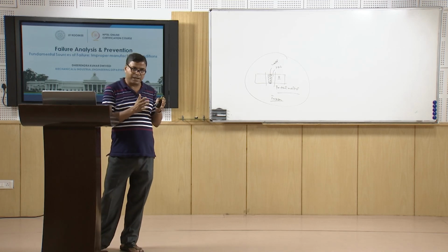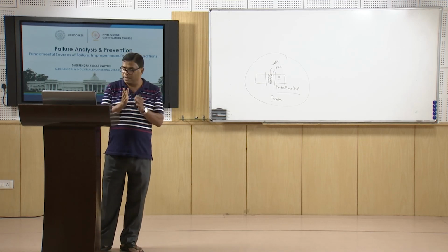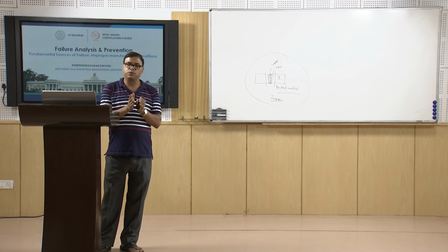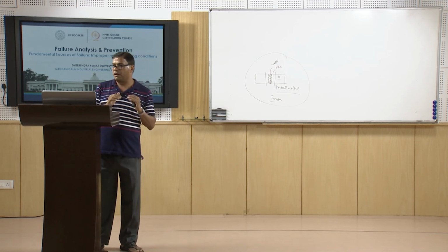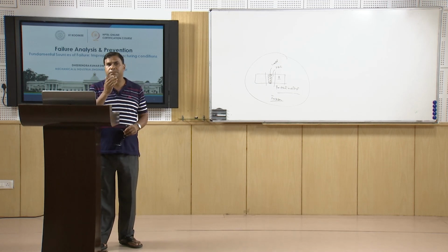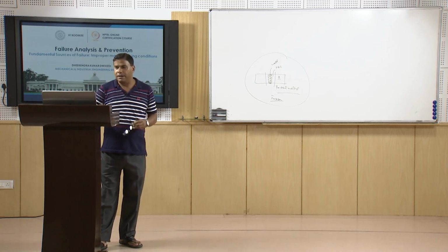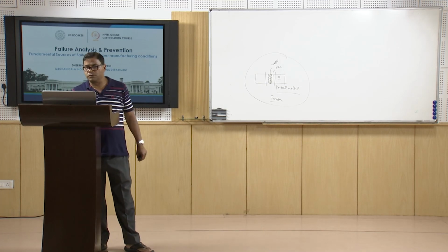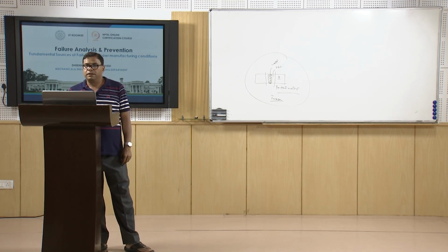At the same time, it has the required set of properties, not just in the weld zone, but also in the heat affected zone. For that purpose, sometimes it may be required to perform post weld heat treatment, so that the properties can be brought to the same level as that of the base metal.